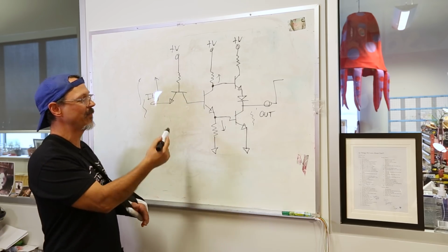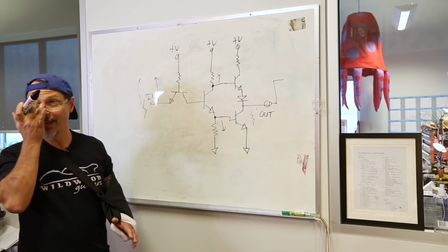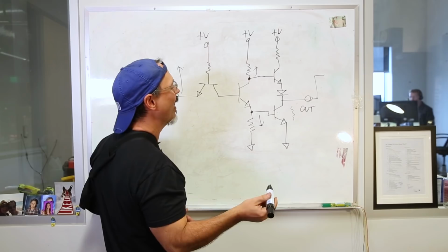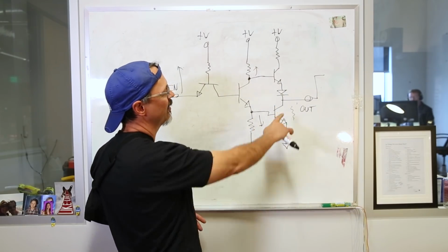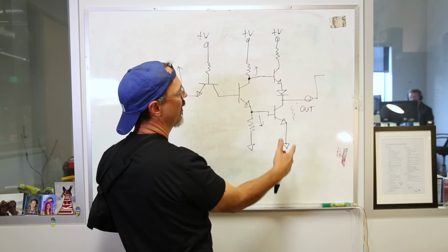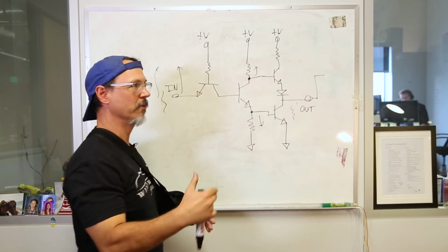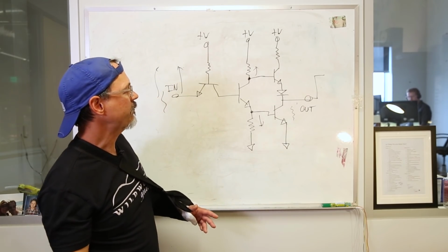When you try to scale something like this up, this kind of thing becomes extremely problematic and it will suck your power and suck everything. It just sucks. Now, in order to alleviate some of that, what is typically done is a diode goes between these. And what happens there is that it raises the turn-on voltage of this component. So there's less time that it's actually turned on, okay?